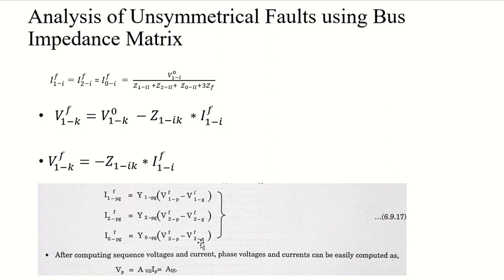You need to invest so much time and brain for all three sequence networks. But once the impedance matrices have been formed, you can carry out your fault analysis very easily for all the buses, right?